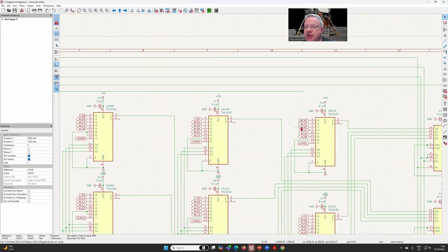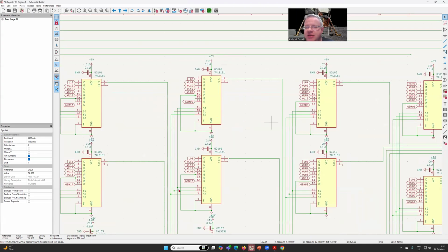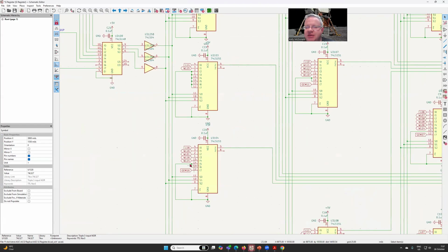And then I can start getting into some of my shifts. In the case of my cycle right or shift right, I write in the contents of write line 2, and I do that in both of these scenarios. The only time it's different is that wraparound. If I go all the way here and look at my 16-bit, if I'm just doing the shift right, I just write in the contents of 16. Otherwise, I wrap around and do bit 1.